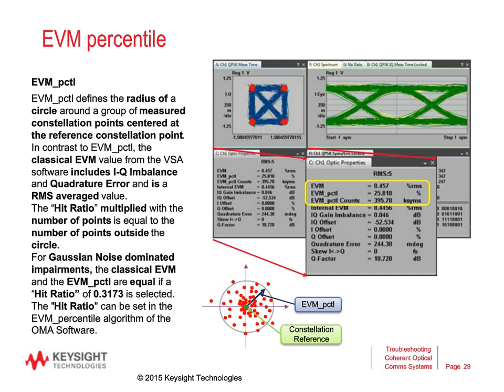I have a zoomed picture below here on that page, rather in the middle, that gives you an idea what I'm talking of, hopefully. We have the reference constellation in the middle as a green point, and the red dots should indicate the measured points that I'm measuring. And now I draw a circle with a specific radius which correlates to the EVM percentile.